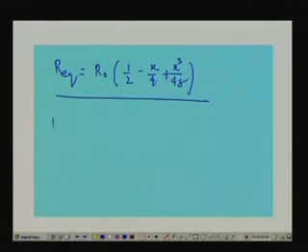Now, we see that x equal to beta delta T by T naught square, which is a very small value. Therefore, x to the power cube by 48 and higher order terms become negligible. So, this becomes very negligible. Therefore, we see that more or less a linear relationship between the resistance R equivalent and temperature change delta T, right.